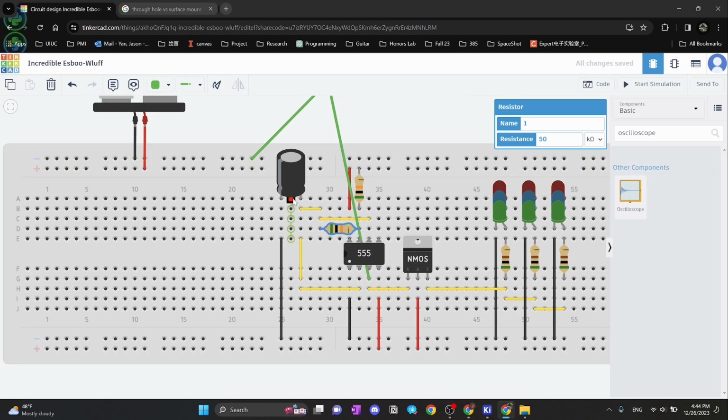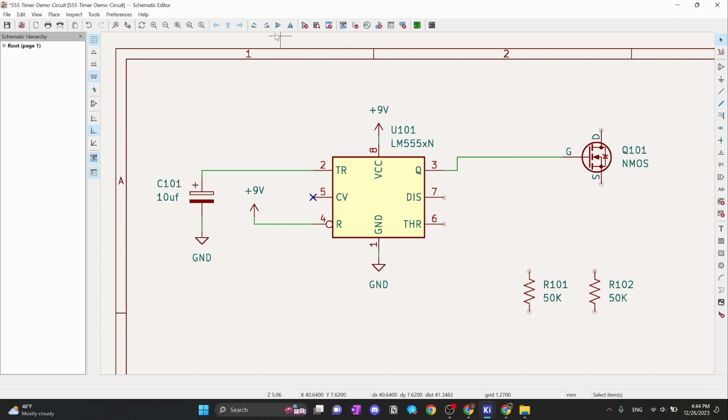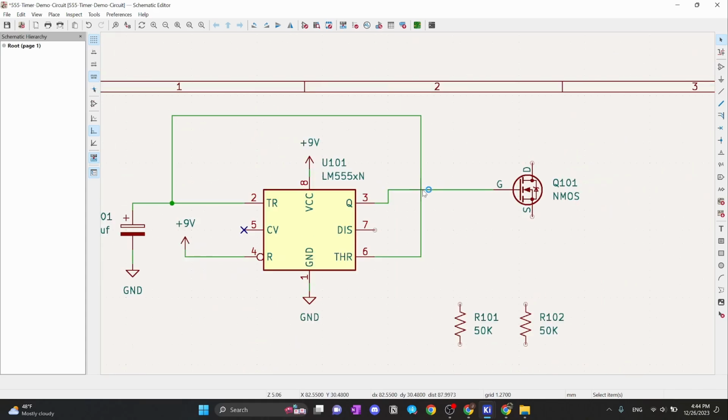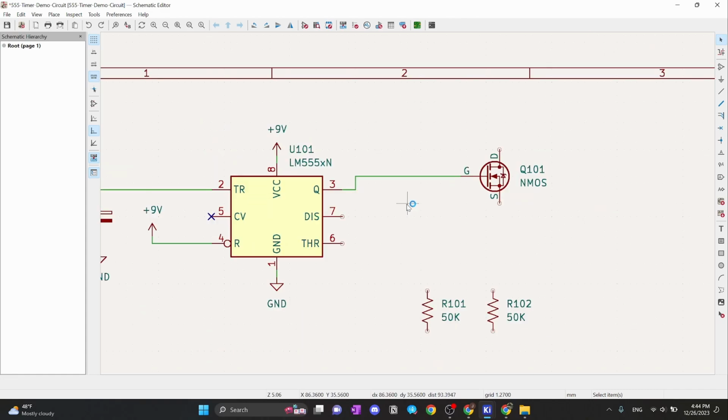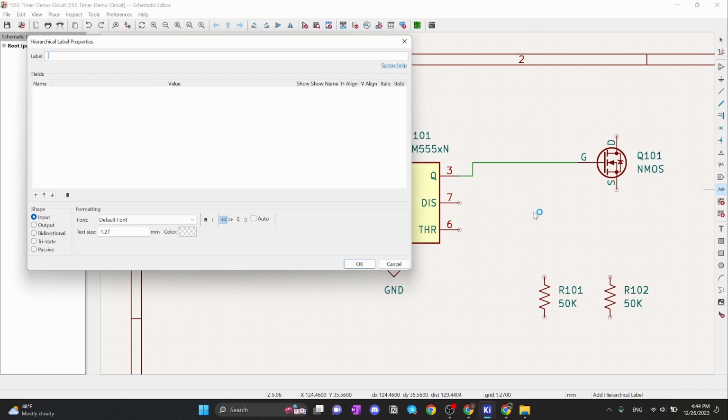But let's just start with pin 6 and connect it to the capacitor first. So, you know, we can definitely do something like that, or like this to make it connect, but it doesn't look very nice. And I would suggest avoiding those kinds of cross sections if you can. It's not like you just can't do that, but it doesn't look as nice. So a simple trick we can use is the hierarchical label. It's basically like remote lines that you can connect to.